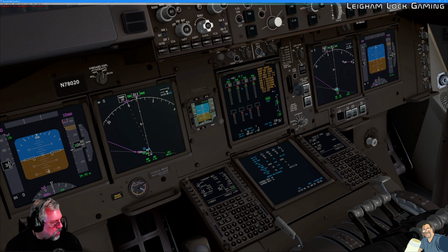At this point, we are pretty much done with programming the flight management computer for this particular flight. We can go back to the legs page, and once the performance data is put in, you can see we start to have our indicated airspeed and our altitude predictions already appearing on the legs display of the flight plan.